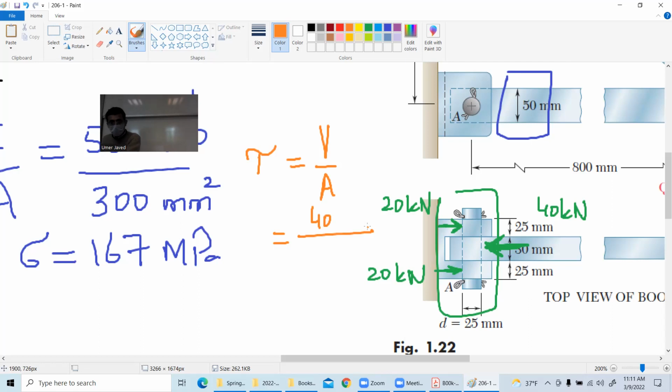Multiply by 2, right? Now it is becoming confusing when this fellow has to break. There are 2 areas, right? One on top. Focus here. It has to break. It can slice from here and slice from here. So now the point of contention is, should I have 2 multiply by cross-sectional area or 1 multiply by cross-sectional area? So let us follow one of the students. He said 2 multiply by pi d square over 4. I will answer both parts of the question. Don't worry. Pi d square. Now you have to give me the answer and then we will do it one more time.